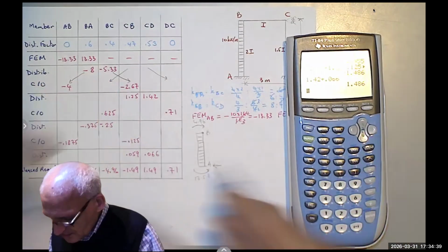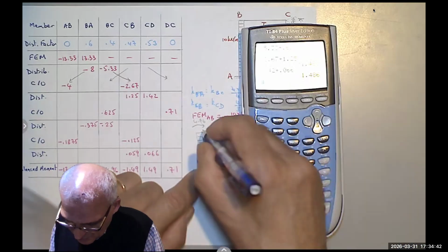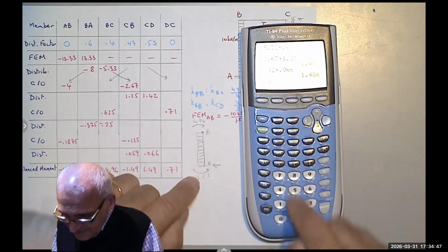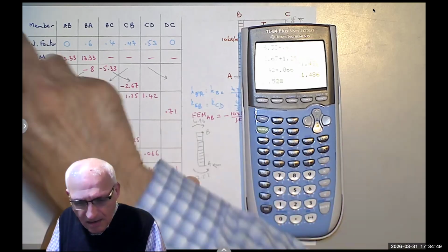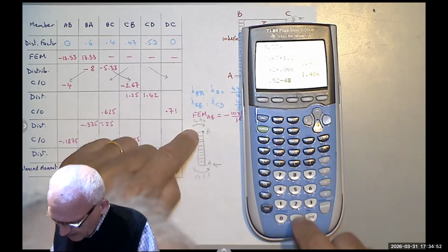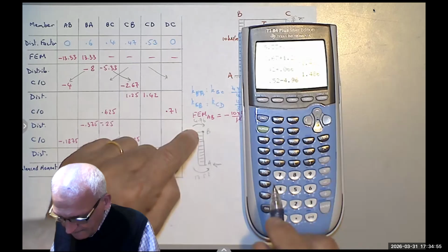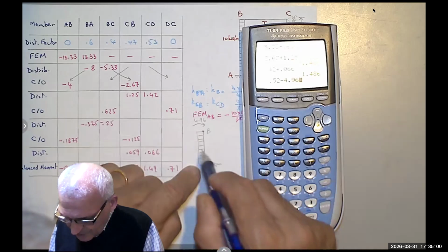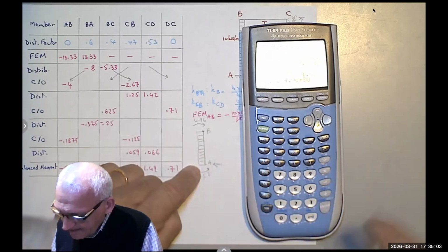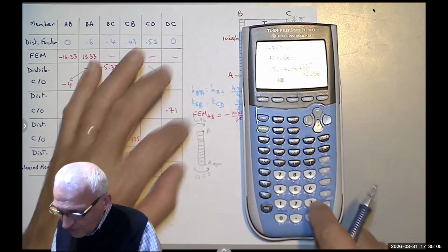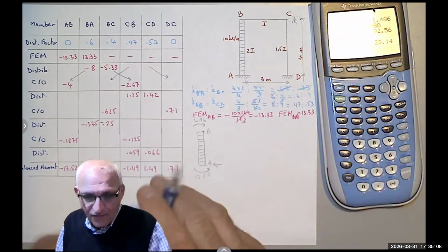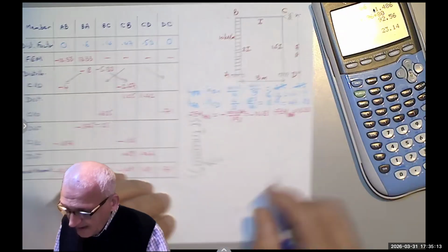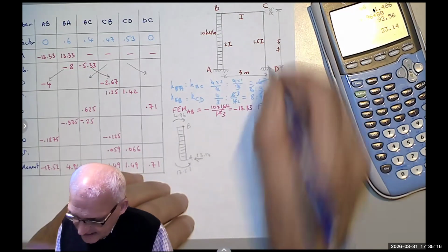Counterclockwise as positive and clockwise as negative. So when I rotate here, I have 1752, then I have minus 496. And then I have 4 times 10 is 40 times 2 is 80, so plus 80. And then I divide by 4, so I get 2314, right? This is 2314. I will do the same thing for CD to calculate DX.